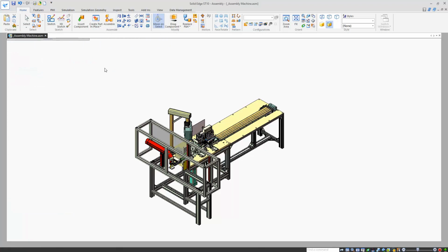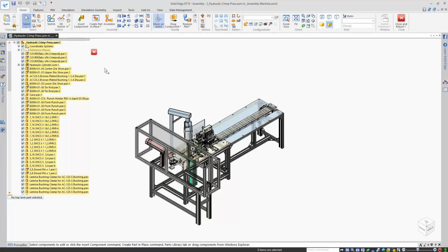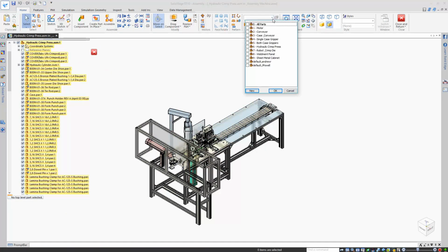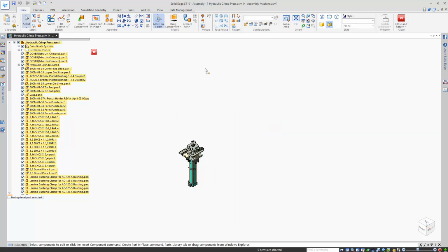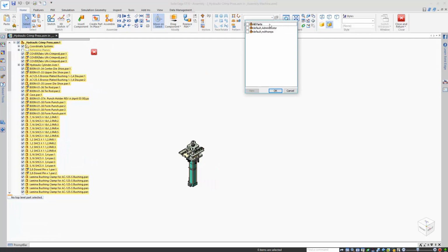If I choose the subassembly and then edit in context, my config list is still the one for the top level. And you might have noticed it still has the new button. That's because we still have the top level assembly open and loaded in this window, and it can only ever access the currently loaded .cfg file, not one for a different assembly. If you hide the previous level with Ctrl-Q, you do get the config list for the subassembly, but because we still have the top level open, as we see in the assembly tree on the side, it's still read-only.